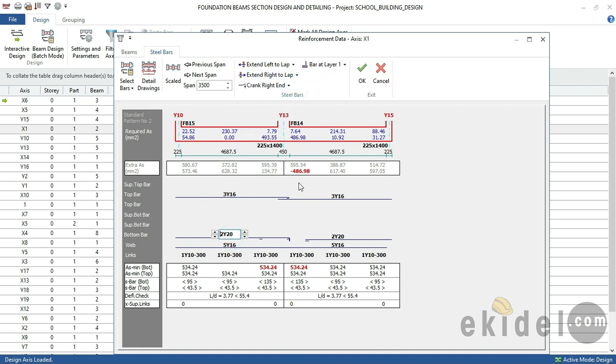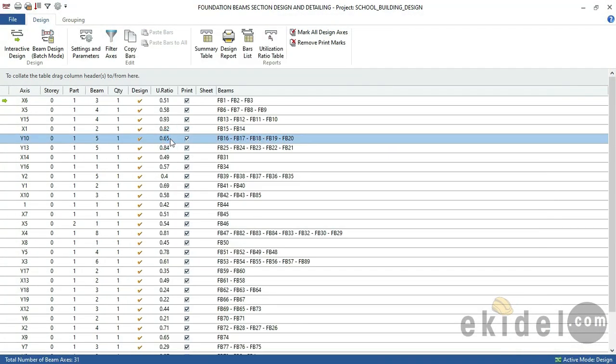So the whole idea is for you to check the beams and do just what I'm doing now. Reduce the size and then increase the number of bars once it's failing. Once you reduce the size, there will be a failure. This thing here means failure, and here means failure. So you have to increase the bar number for you to be able to pass, and then it is okay. So you can go here right now, click on OK, and then go. Let me just go again.